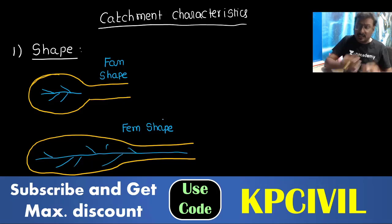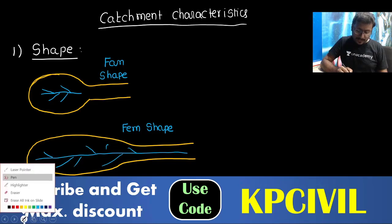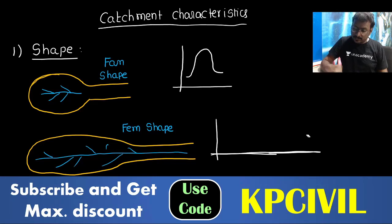Fern-shaped, very long. Branches are at different locations. Which is having more peak discharge? Tell me. Fan-shaped catchment is carrying the highest peak, more peak discharge. Fern-shaped catchment is carrying a lesser peak and shows some fluctuations also, like this.